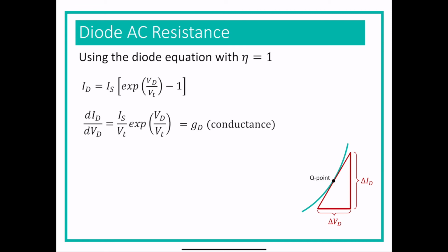So we can take the thermal voltage and combine equations a little bit. The equation I'm going to put up is exactly the same; all I'm going to do is put the thermal voltage all on the bottom. Then let's look back up at that top equation for a second, because we had ID equals IS times the exponential of VD over VT minus 1.